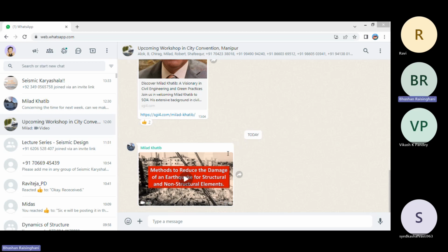All longitudinal bars along each diagonal shall be enclosed by special confining transverse reinforcement as per section number 8 at a spacing not exceeding 100 mm. So this spacing should not be more than 100 mm. It is special ductile detailing as per section number 8, as for the beams that we are doing.